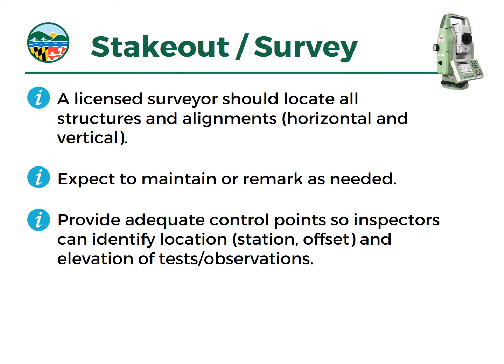I'm sure all contractors have a surveyor who they've worked with. So we recommend having a licensed surveyor locate all structures and alignments, mark them out, and expect to maintain those marks as construction goes along. Marks will get damaged. I don't know why, but it feels like bulldozer blades have some kind of magnetic attraction to survey stakes. They get knocked over quite frequently.